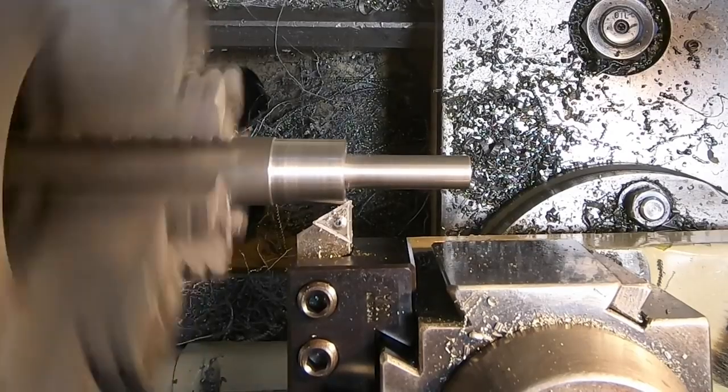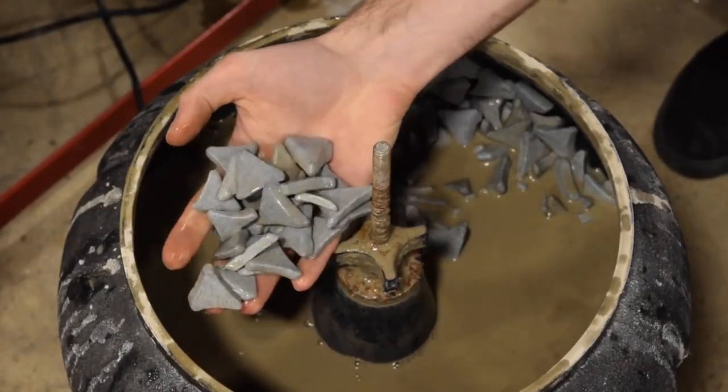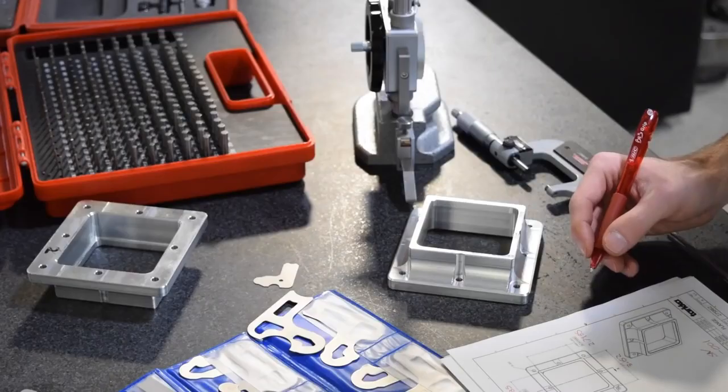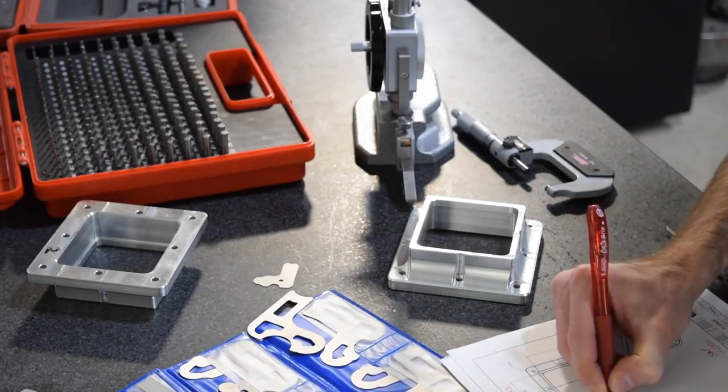If you use a note like this, you've given them the option to deburr on the machine using a hand tool, grinder, bead blast, or a vibratory finishing machine. But if you place dimensions in a view to specify the edge break, you've pretty much forced them to machine it, and it becomes a feature that has to be held to a tolerance and must be inspected.